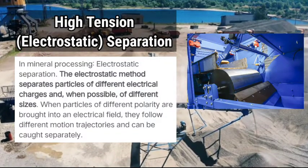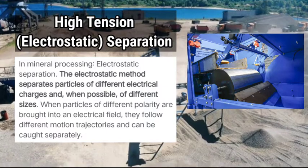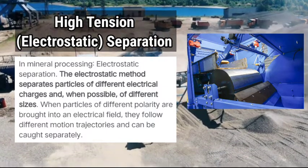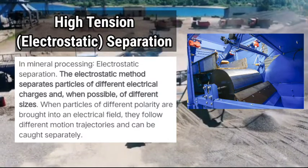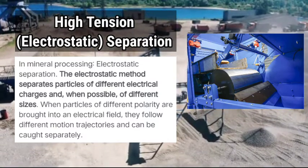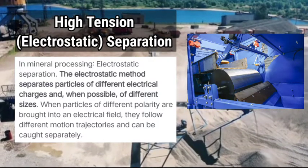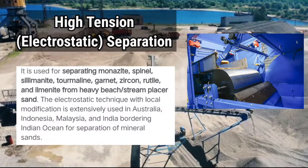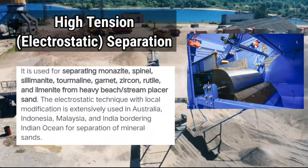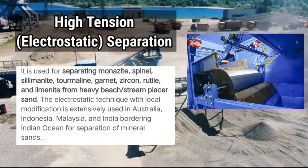High tension separation. In mineral processing, the electrostatic method separates particles of different electrical charges and, when possible, of different sizes. When particles of different polarity are brought into an electrical field, they follow different motion trajectories and can be caught separately. It is used for separating monazite, spinel, sillimanite, tourmaline, garnet, zircon, rutile, and limonite for heavy